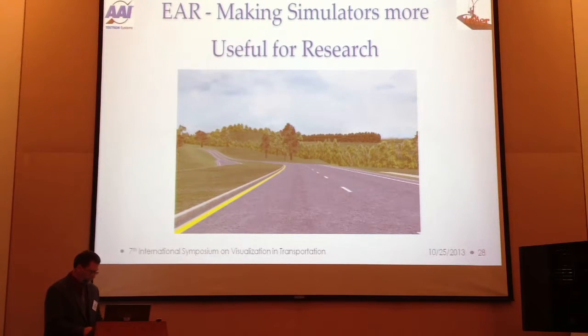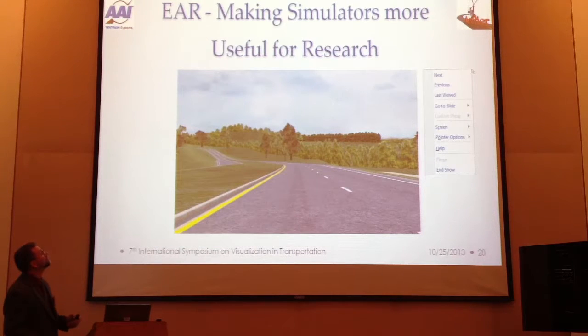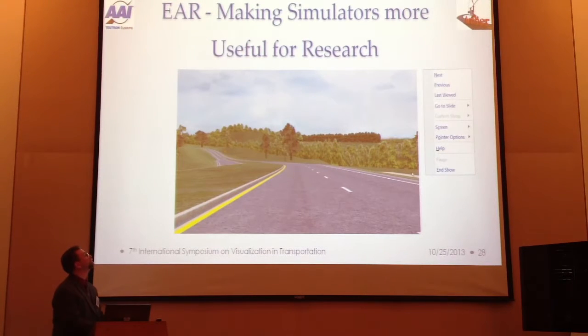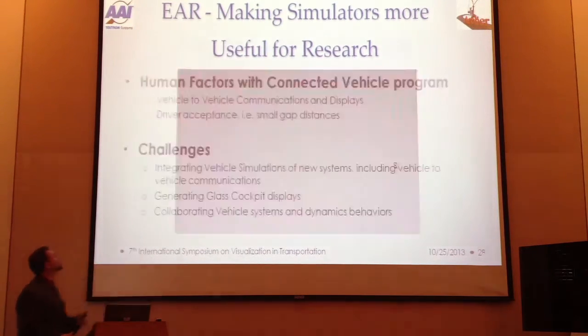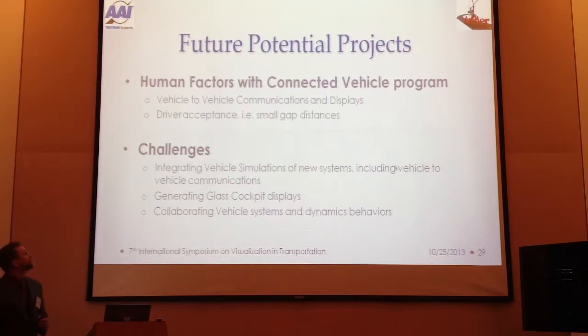But this is one of the problems with this particular roundabout when they first put it in. There's almost a reverse super elevation on the roundabout, throwing people off as they're going around it. And you could feel that in the driving simulator in the motion base. You could feel it kind of kick you out to the side, just like it did in the real world. So almost done here.